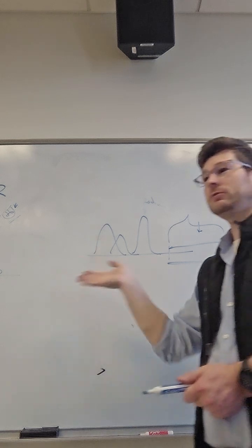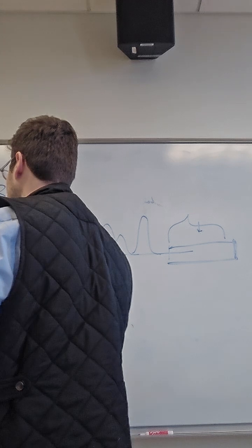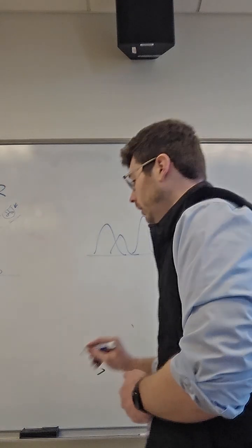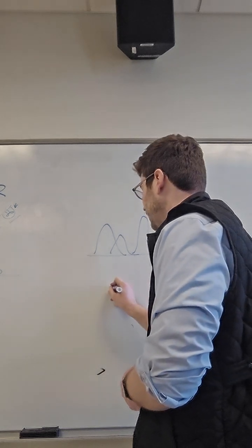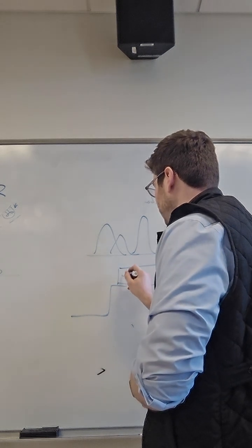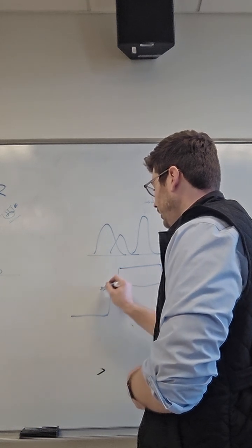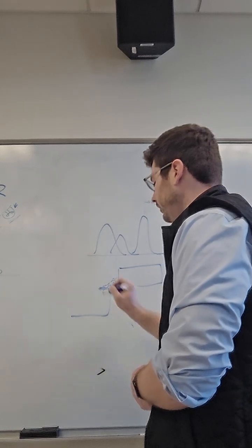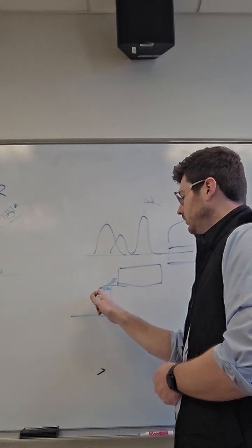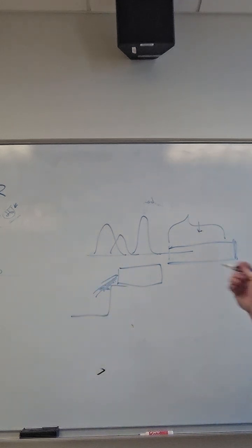We can do presence detection, right? Is the hand there or not for sinks and things? We can do distance detection, right? Little robots, seeing how close they are to walls. Or Roombas actually use this for fall detection, okay? As they're approaching a step, the reason that they don't fall down the stairs is because they are putting out a stream of IR light. And it can see whether or not that gets bounced back by the floor that's underneath it or not. And if it sees that it's not getting that light back, it's being projected into nothing, it's looking over a stair step, and it shouldn't continue in that direction.